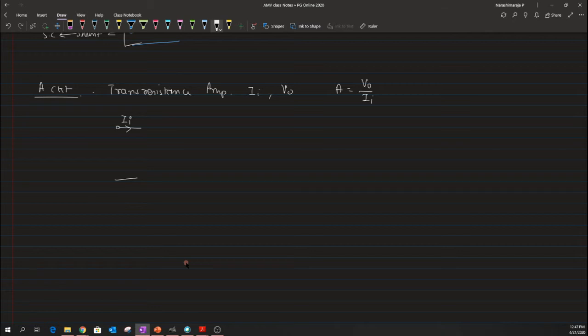The source resistance Rs can be brought directly, and the value of R11, which is equal to Rf, also goes in parallel, and we also have an impedance RID, the input impedance of the op amp. If you want, I can just draw this.